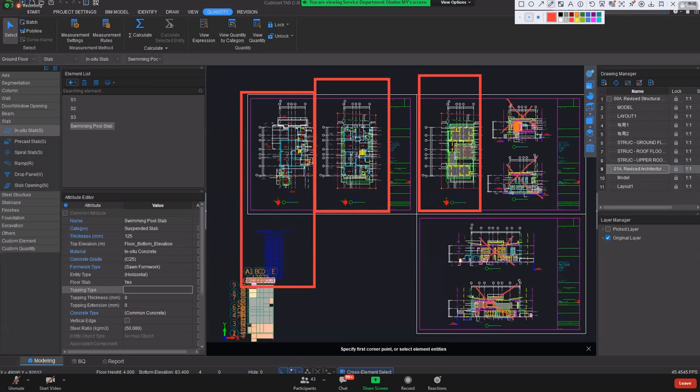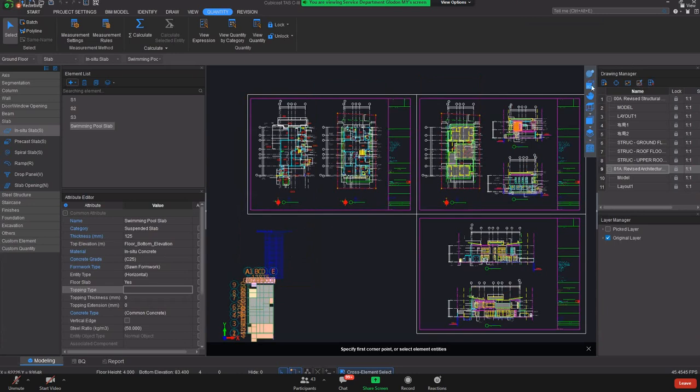Please, the first part, if you split together, you just left click and drag everything with the door and window schedule also. Don't worry about the below model. You won't be able to select. Don't worry. Second part and the third part. Let's practice. How to split? The first step, the fourth button, right? Split it. Select the CAD entity.